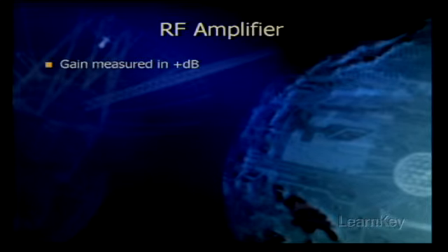Sometimes the DC voltage which is used to power up the radio frequency amplifier is called phantom voltage. And the reason why is because the radio frequency amplifier will sometimes seem to magically power up. Now, the DC injector is actually powered from an AC voltage wall outlet, so it might be located in a wiring closet, and that's kind of why we see this phantom voltage occur. In this scenario, the radio frequency cable will carry both the radio frequency signal and the DC voltage, which is necessary to power the inline amplifier, which in turn will boost the radio frequency signal amplitude when it's applied.